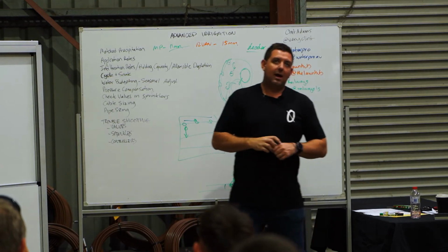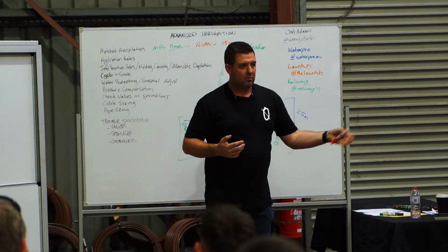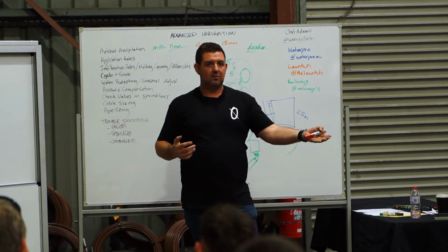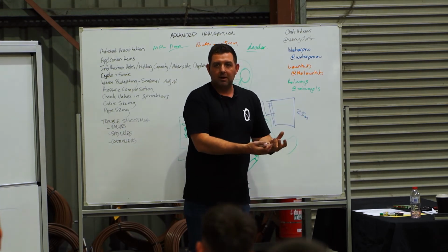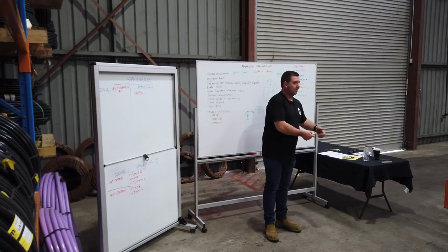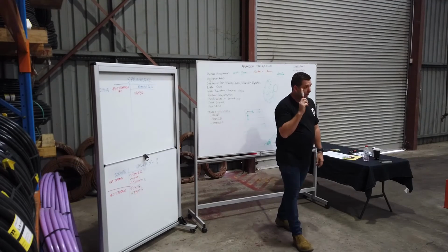Another reason you might have no flow is a damaged pipe leading to the sprinkler. Obviously there's not enough water getting to the sprinkler. In those cases, you'll generally see bubbling underground, or water squirting out somewhere, or a puddle somewhere. Or you won't, and you'll have to listen for it.